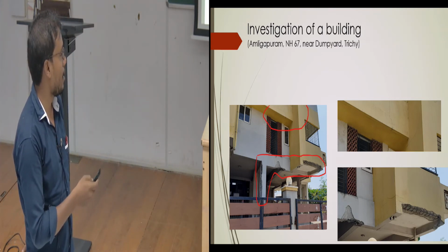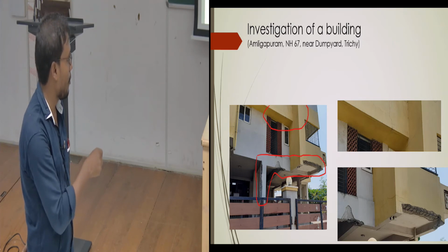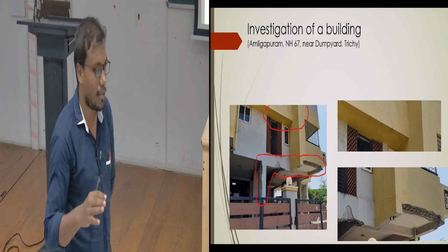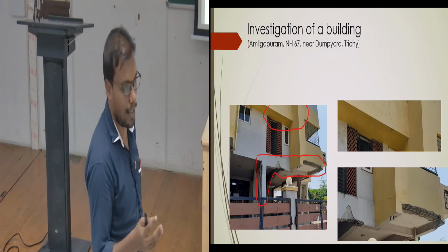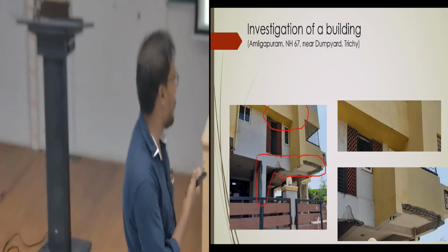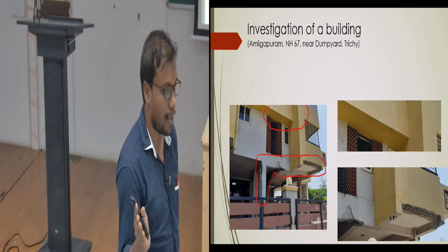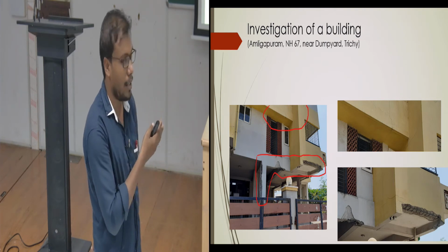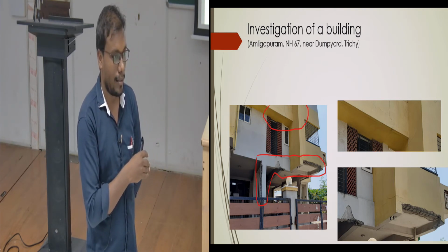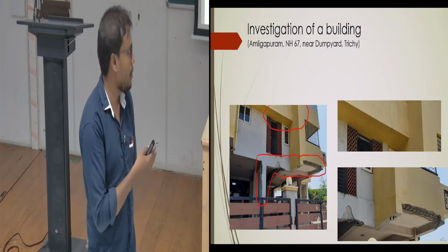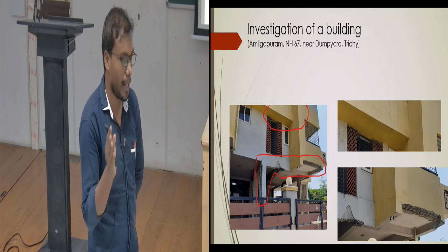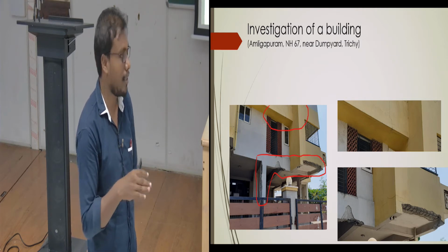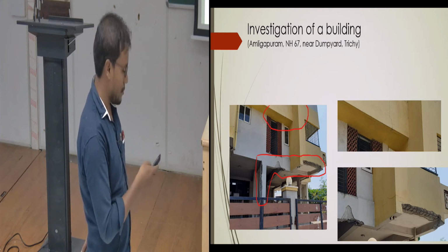So actually, besides this, I visited more buildings, but no cracks were there. No cracks were there in that building. So I thought so many cracks were because of that dump yard effect, but that was not the case. Actually, this may be because of the poor material used. Because if it was because of the dump yard, then other buildings might have been affected, but that was not like that.